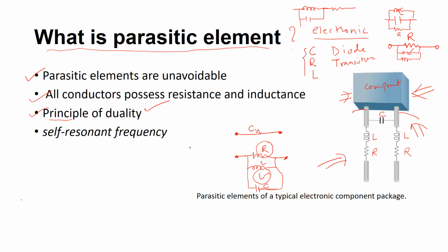For example, you have an inductance and it is not a pure inductor. When you manufacture a coil, its symbol is as shown, and it has a certain number of turns indicated by N. Since this inductance is not pure, it will have a capacitance as a parasitic element. At a certain frequency, this L and C will form a tank circuit that will get tuned or resonant at a specific frequency.